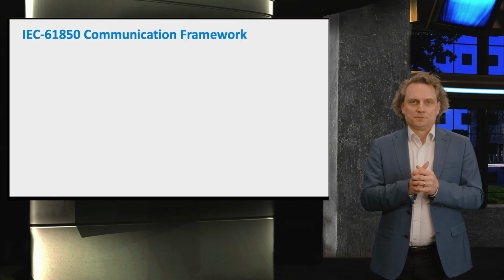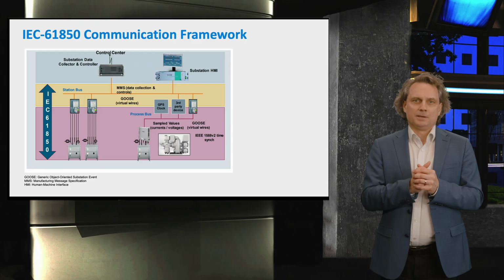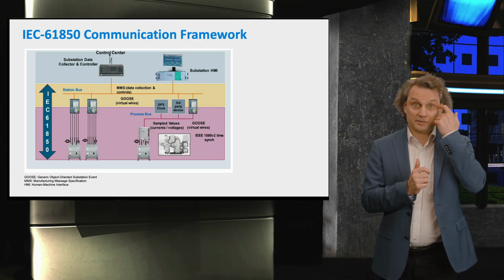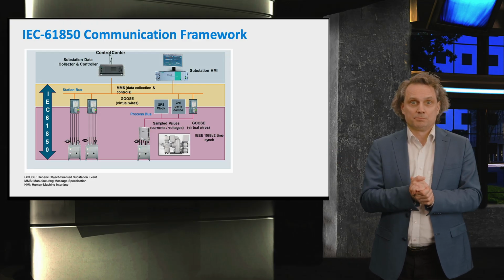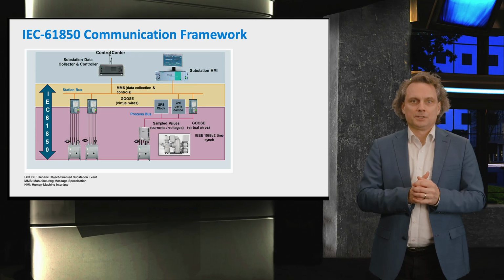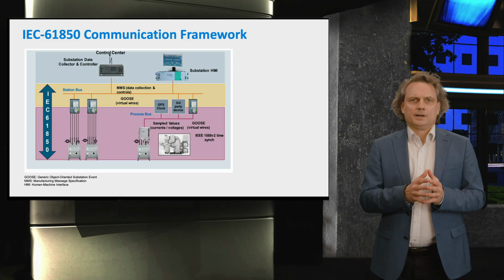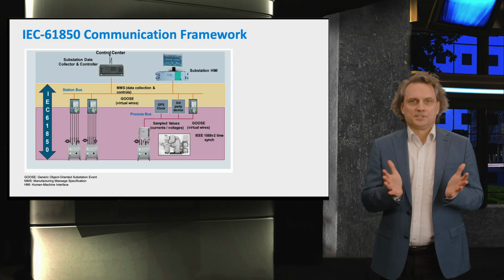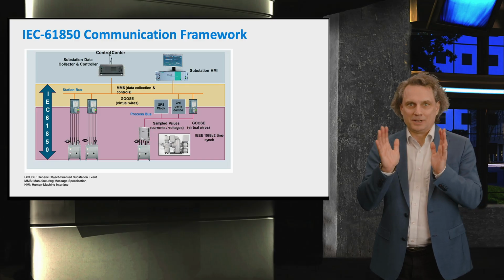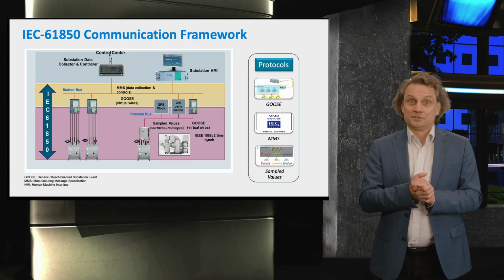In a digital substation, you will find maybe a station bus that covers the entire substation and process buses that are for certain applications such as a transformer. Both are covered by the IEC 61850 standard. The standard itself contains many subchapters, including a number of specialized protocols.